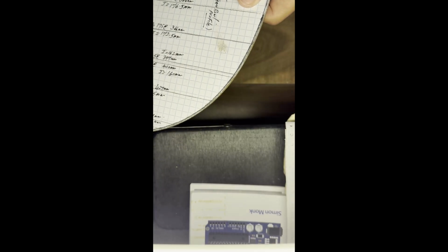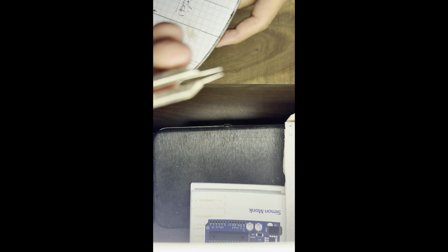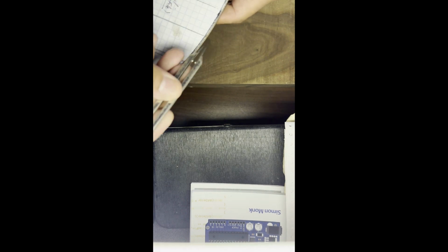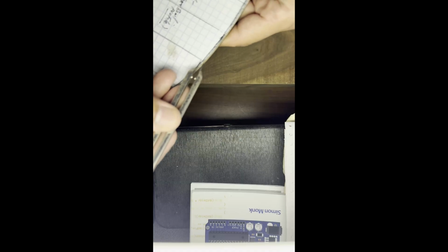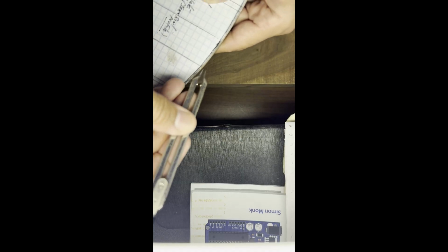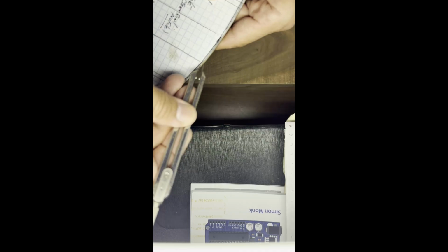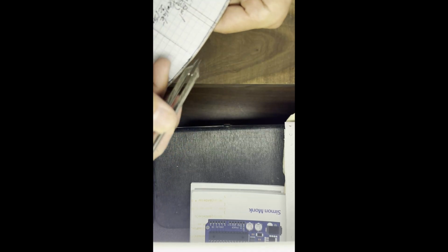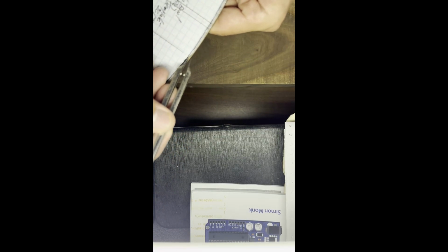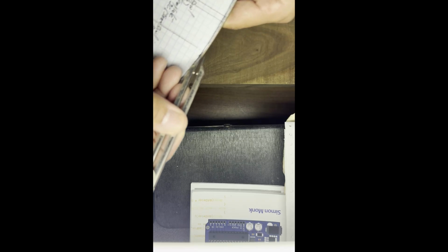And then in addition, what also helps is that you go back from the other side. So you open your divider, you set your divider to the thickness of the rib, and then on each one of these points, you keep the divider and you re-verify and make sure that it's equal, in my case, the 2.5 millimeter all the way through that secondary curve.